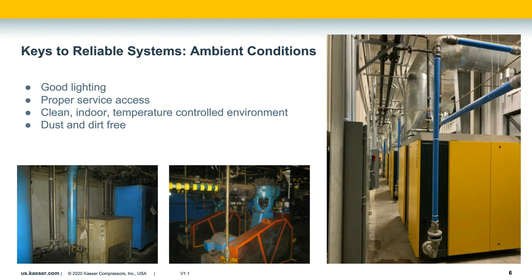All your equipment has operating temperatures, maximums and minimums. So if your compressor room doesn't have minimum heating and the compressor's off, this can cause freezing issues within compressed air piping or even within the compressor. And again, dust and dirt can build up and affect compressor performance. So if there's a significant amount of dust and dirt in your environment, this is going to increase your service intervals.